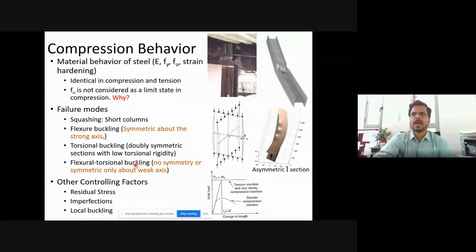For different types of sections. However, for angles which are connected through only one leg, the code says that you cannot avoid flexural torsional buckling. Do not use the phrase lateral torsional buckling for columns. Lateral torsional buckling applies only to beams. For columns, the similar phenomenon is known as flexural torsional buckling. I misspoke there. So the failure mode is flexural torsional buckling of columns or compression members.